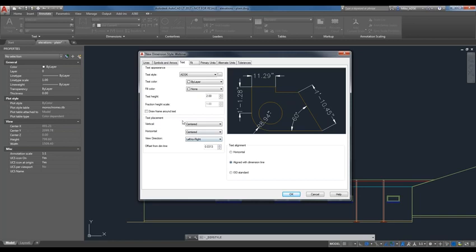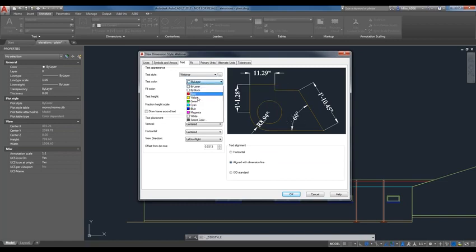So going over here to text, this is what I was mentioning before. The reason that those text styles are so important is because you end up using them later on. So this is the webinar one that we created earlier. You're going to notice that the numbers did change to reflect that now our font is Times New Roman. Go ahead and change the color if you would like. So this text height over here was what I was mentioning before. Since we set it to 0, we could go in and change it to whatever we want now.